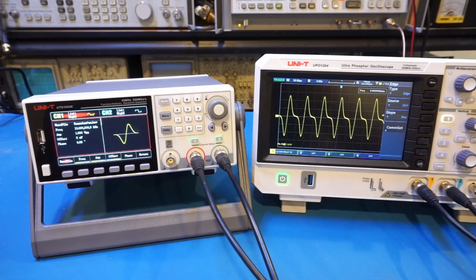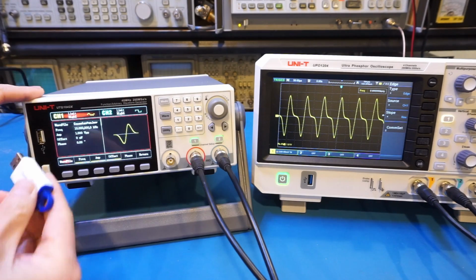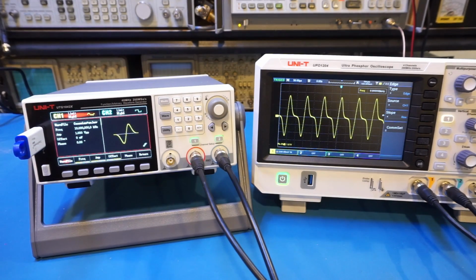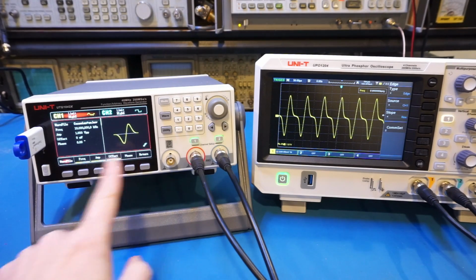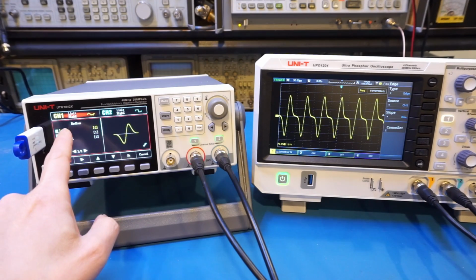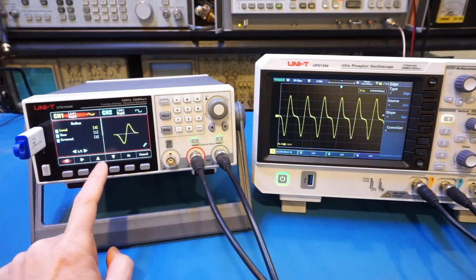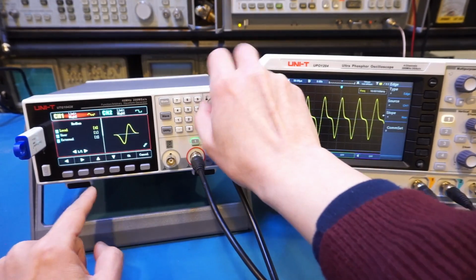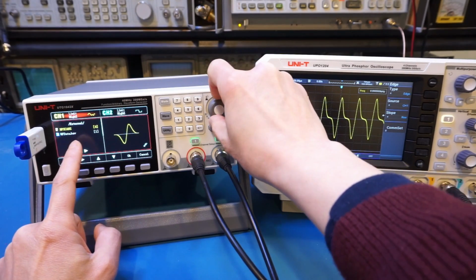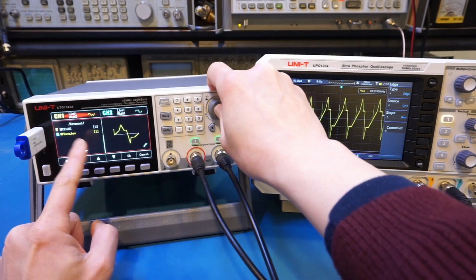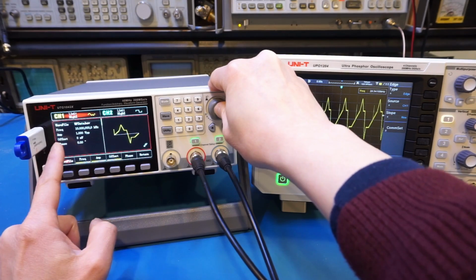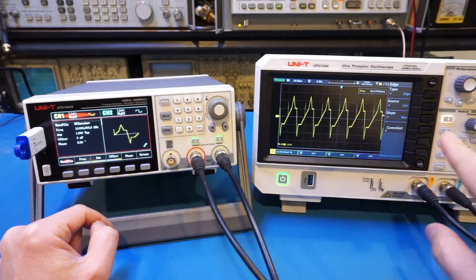Now I have designed an arbitrary waveform earlier, and I have put it onto the USB drive here, so let me plug it in. And once you plug it in, you see the icon here that indicates that the USB file is recognized. So let's go back to the WAV file here. And you can see now, besides local user, we have this external. So let's go to external, and here you can see that we have this wave data.bsv. That is our saved arbitrary waveform. So let's hit OK. And now you can see we are displaying the arbitrary waveform on the oscilloscope here.